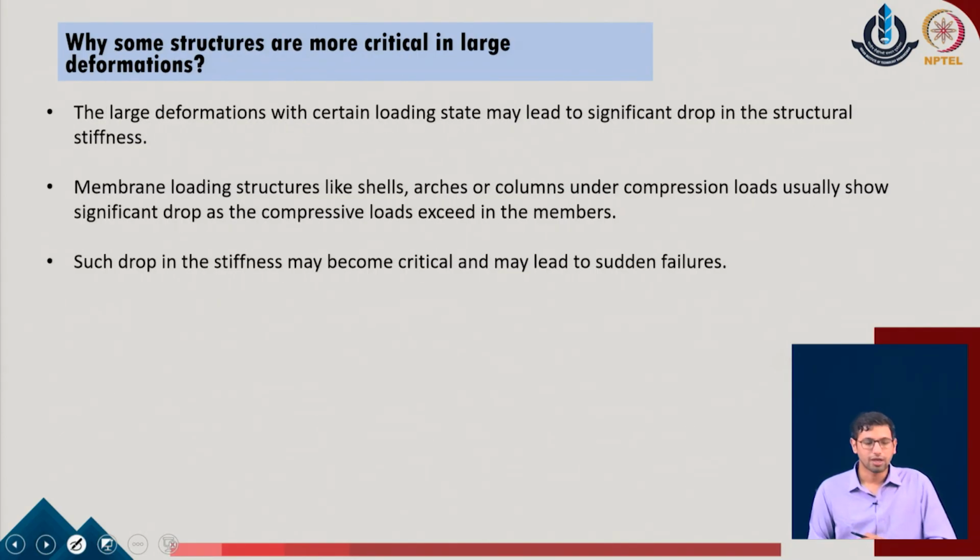Now, moving forward, we have the next case, in which we consider why some of these structures need to be considered critically for large deformations. Large deformations are required for the design as well as the analysis of certain problems, but at the same time it may become much more critical for some of the members, because these members, as they modify their stiffness with the increased deformation, can go into such a range where the stiffness drop becomes significantly critical for the system.